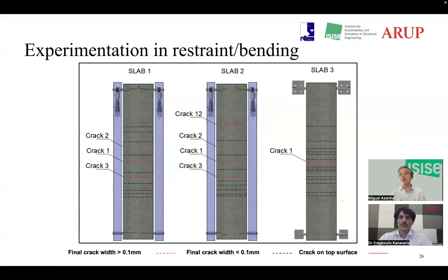So slab number one clearly cracked more, of course, as it was more restrained and with more load, and yet the cracking was actually bigger than the crack that we anticipated when we overlooked the shrinkage. Yet it was not that much bigger. And then this was the ground for next research that happened. But still, for those wanting to go deeper, this is published material where we even have simulations where we learn more about it.